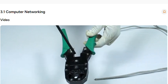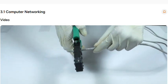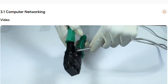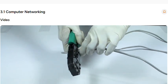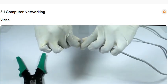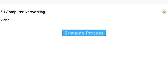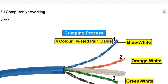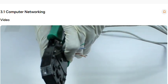Insert the cable in the blade area of crimper tool and pass it around 1 inch outside the crimper tool. Now hold the cable and carefully cut the outer plastic protective cover without damaging the wires. Remove the outer plastic protective cover carefully, and now you can see 4-pair twisted cable and also cable fiber to add strength to the cable. Now cut the cable fiber using crimping tool.